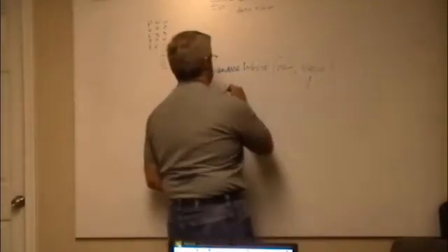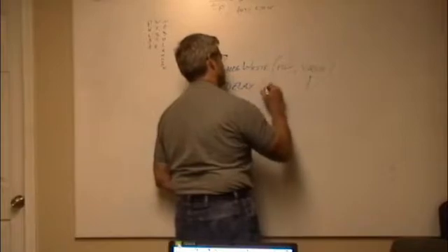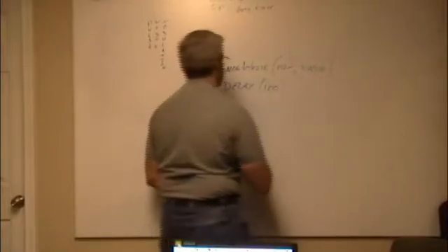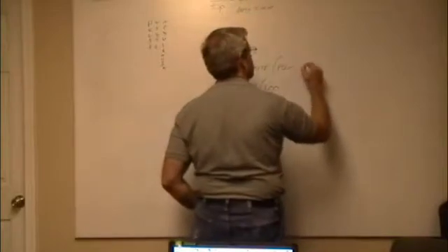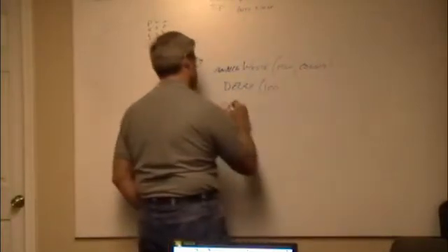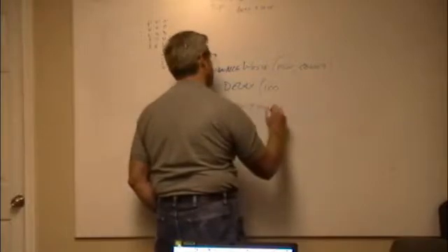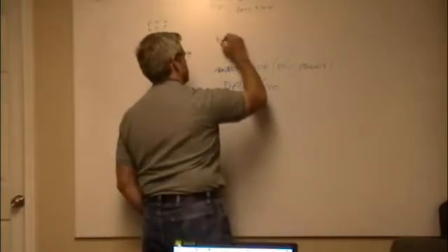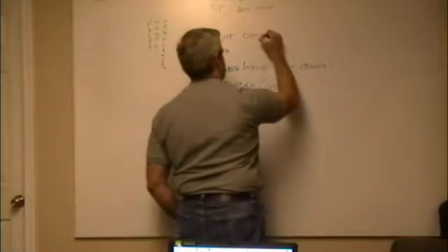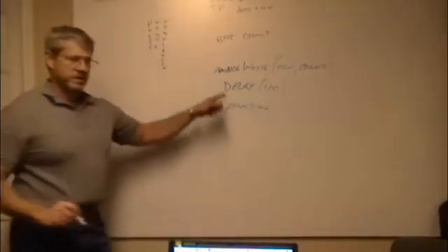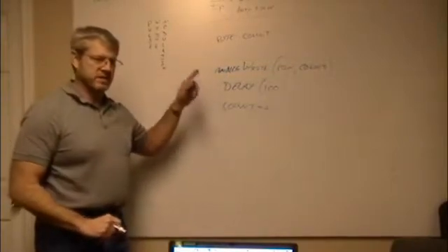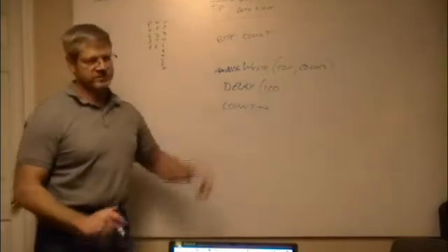So this little piece here is analog write, and then it's delay 100, so for 100 milliseconds, and then value is count, and then it's count plus plus, and it's a byte count. So here we're taking advantage of the fact that it's a byte, it's 8 bits. When it hits 255, when it plus 1s again, it'll wrap over to 0. And it should be a tenth of a second between each one.